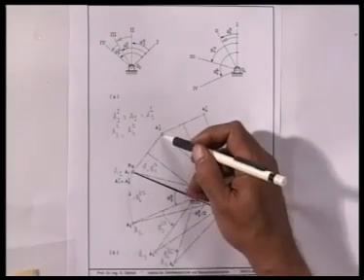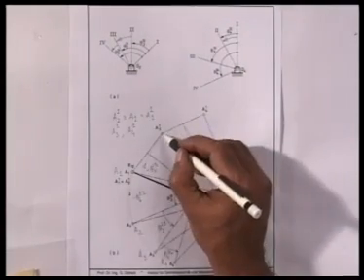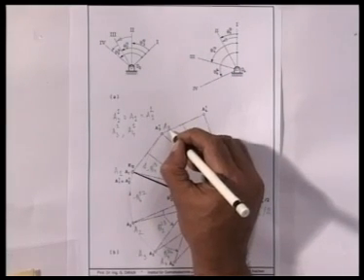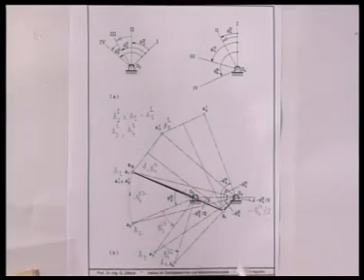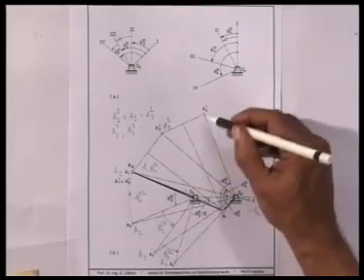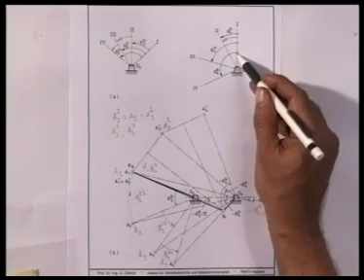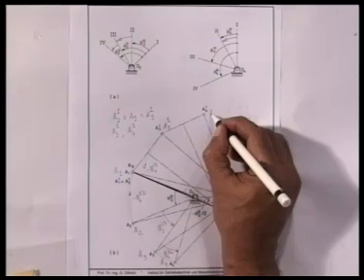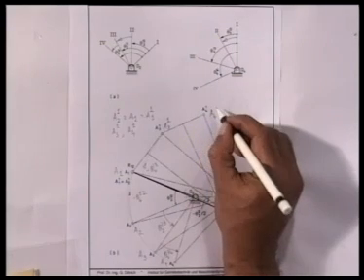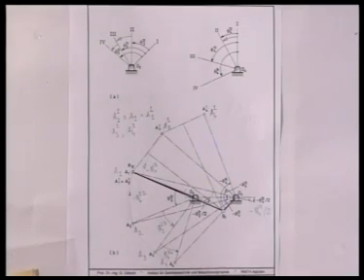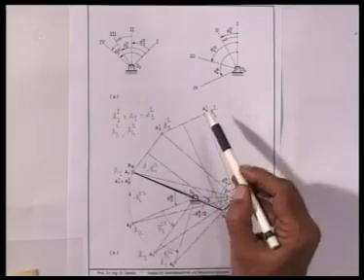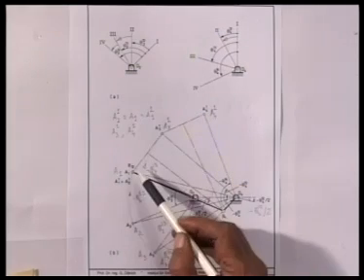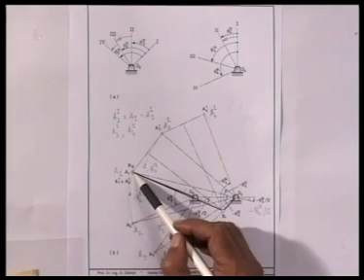So, I rotate it clockwise because it is minus theta 4 1 3, and I get what I call A31. Then rotating O4 A4 through minus theta 4 1 4, which is counterclockwise, I rotate it clockwise and get the inverted position of A4 as A41. So, you see, for the 4 inverted positions, I have only 3 distinct locations. This is A31, this is A41, but A21 and A11 are coincident.